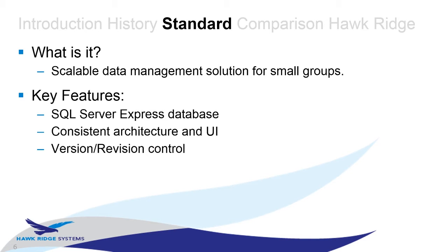Version and revision control. One of the biggest headaches a lot of workgroup customers experienced was having to worry about the revision management when they moved away from Workgroup PDM to PDM Pro, or in that case, at that time, ePDM. Because PDM Standard and PDM Pro are using the same architecture, your versioning and your revisioning will be exactly the same. Your history will still be built in. You won't have to wipe and start fresh. It's all going to be built in for you.